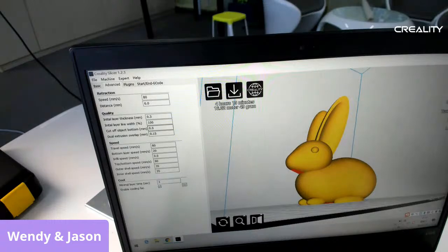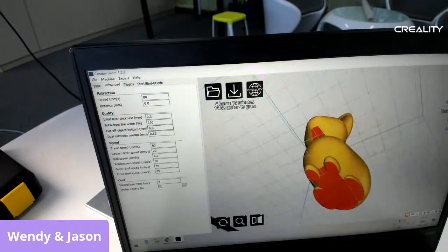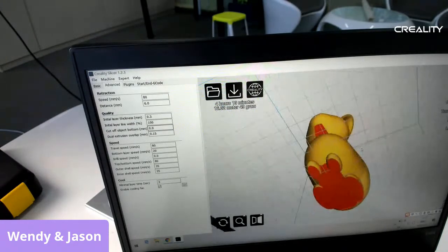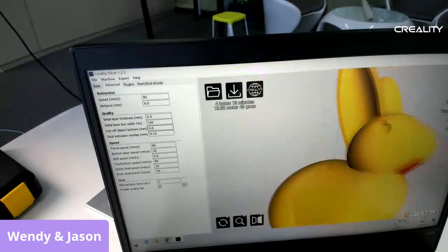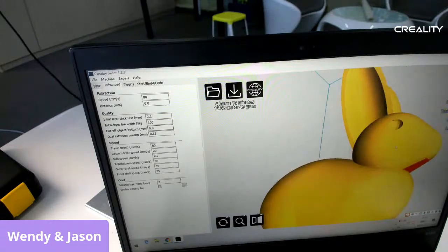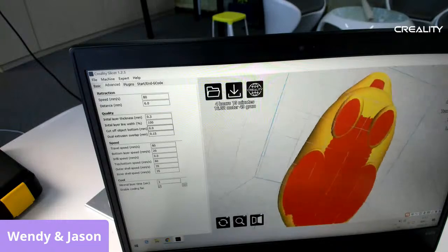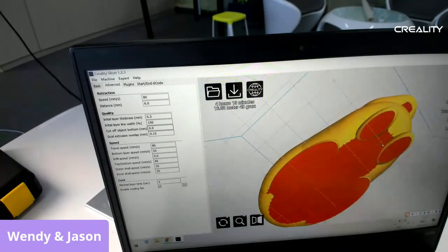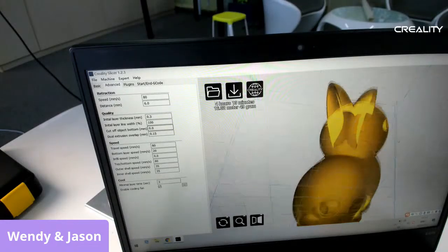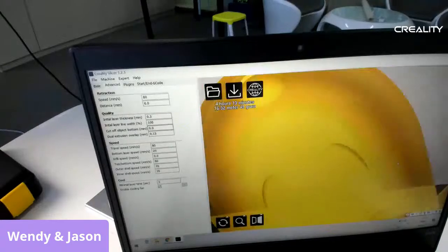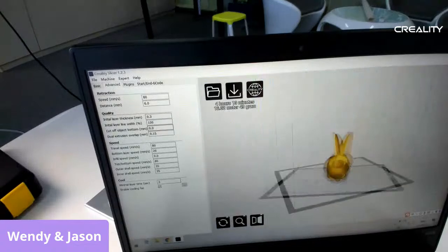There we go. So the overhang shows you the red zone. We colored it red to show which parts are dangerous if you want to print it. It's probably going to flow down. So for those red zones, you either need support or a base, just to stabilize it. It's just like Chrome. And it's transparent, so you can actually see inside. There's not much detail inside this product.